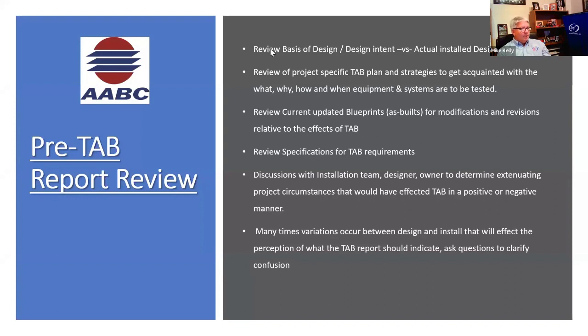Is all the ductwork 9 feet above a drop ceiling, and no ladder in the world will get you 9 feet above the ceiling to adjust the dampers? We need remotely operated dampers or an accessible ceiling that will allow a ladder or scaffold to get to that. Balanceability is the idea of those strategies and the equipment: can we get to it? Can we balance it? Are the filters accessible? Can we get to adjust the outside air and return air dampers, or even perform testing?